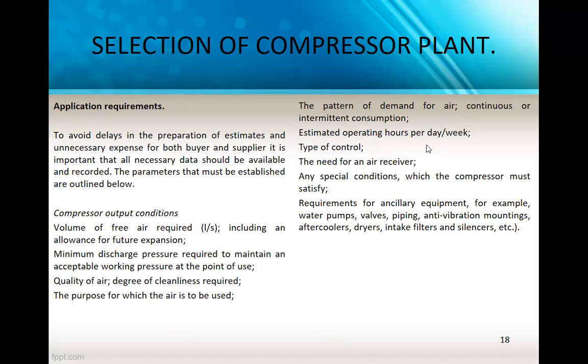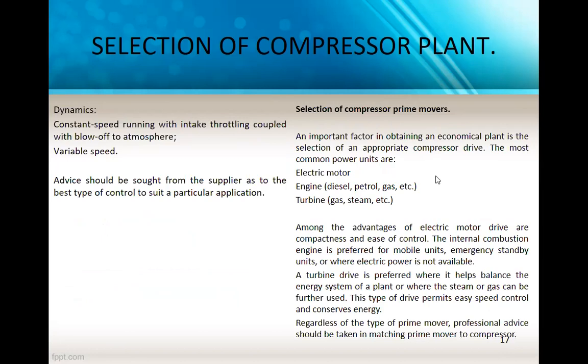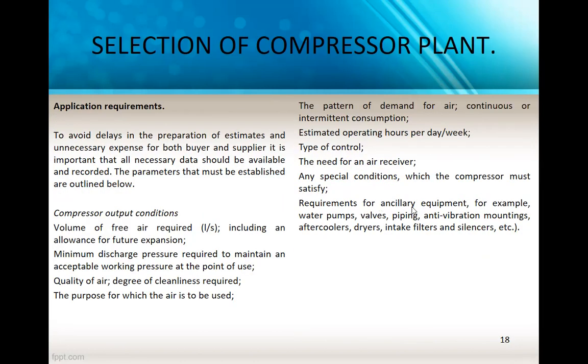Estimated operating hours per day or week. Type of control. The need for an air receiver. Any special conditions which the compressor must satisfy. Requirements for ancillary equipment, for example, water pump, valves, piping, anti-vibration mounting, after coolers, dryer, intake filters, and silencers.